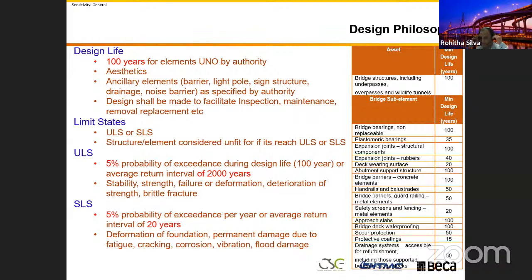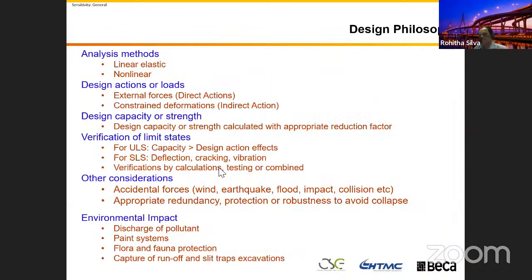Because when you are learning things at university, or in your practice, you use the ULS and SLS and always work with load factors, but when you are designing bridges, you work around the environmental loading, like wind, earthquake, and flood. Then we talked about the return period and the probability of exceedance. So that's where we work. Then analysis methods, linear and nonlinear. I haven't gone into detail in this area, but during the bridge modeling, I'm going to discuss it in a bit more detail.